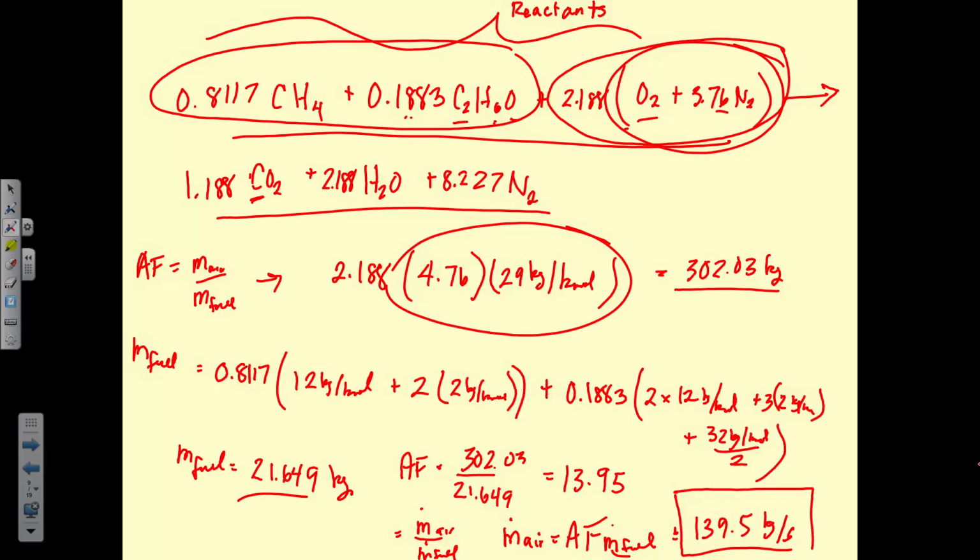Any questions on this process? So in this example, it showed how to go from a mass-based analysis to a molar analysis, and then using that molar analysis to figure out how much mass flow rate of air is required to get complete combustion with theoretical air.